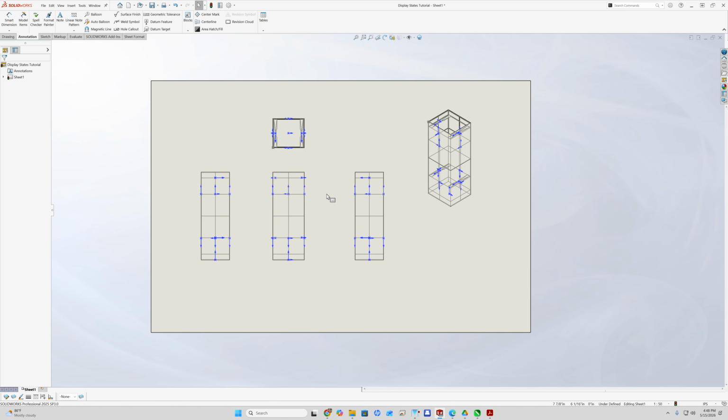Now what's all this blue stuff? Well, that's if you have your sketches visible and so on. Hopefully you know what that means. Already this tutorial is going longer than I wanted it to. But the thing I wanted to show you now was, of course, I could get rid of the stop signal that's popped up by either going up here and hitting this, rebuild, or it tells me to do Control B, but I like to do a full rebuild, Control Shift Q.